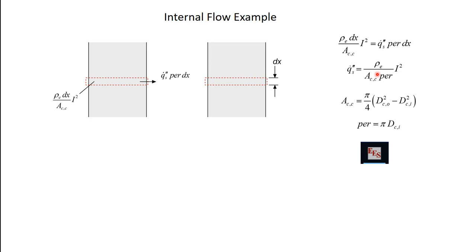The other way I could go at this point is to say, well, there's so much conduction, this is so conductive in this direction, that there is no temperature gradient in this direction because that conduction is so strong. And then I would have a different limit, which would be that the duct experiences a constant surface temperature. So we have to go one of these two ways. Again, which of those is more right has to do with what the resistances involved are. At the very end, we'll go back and look at these resistances and decide whether this is the right way to go or the constant surface temperature limit is the way to go. This is the one we're going to use for now. So I can do these calculations.